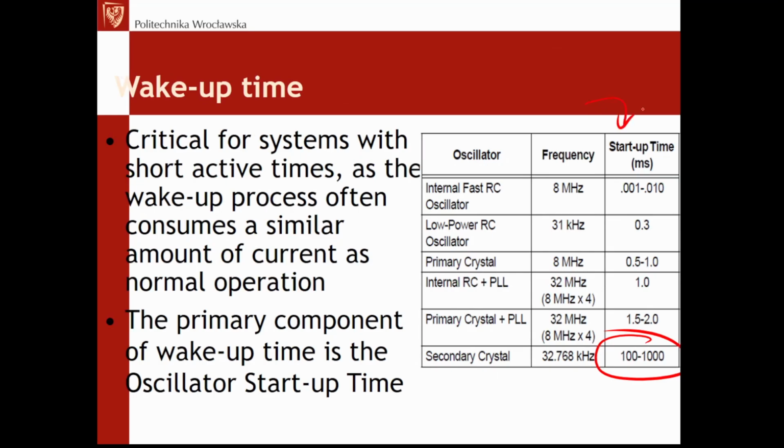Naturally, waking a system every week is an extreme example, but normally we talk about systems woken up every second, or 10 times per second. And if this is 10 times per second, the system is to work for 10 or 20 milliseconds after each wake-up. Then again, we must think twice when using this kind of combination.